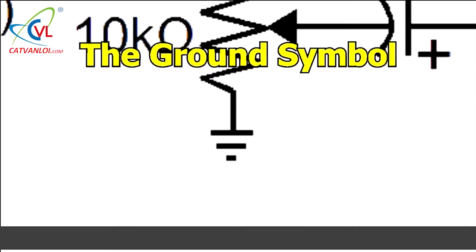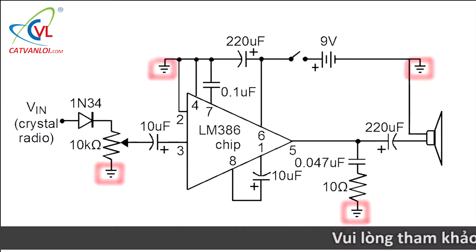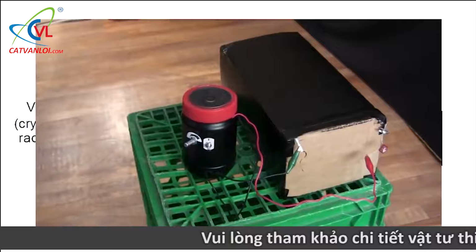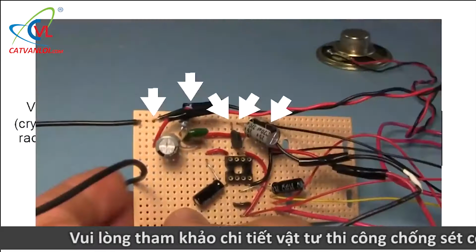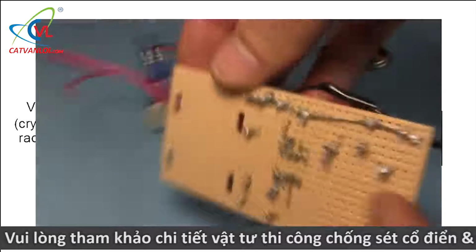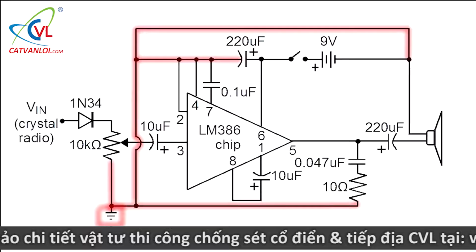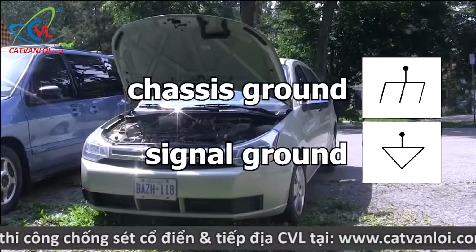And finally, what about this ground symbol in the schematic for an electrical circuit? Well, it's called ground, but very often it's more of a common reference. For example, this schematic is for this amplifier. Notice that it doesn't contact any ground. In that case, it just means that all of these points are connected together. For the circuit board, I soldered all those points to a bare wire in the back. Anything connected to that common reference will have voltages that are relative to that common, a sort of zero for that voltage. There are other ground symbols too.